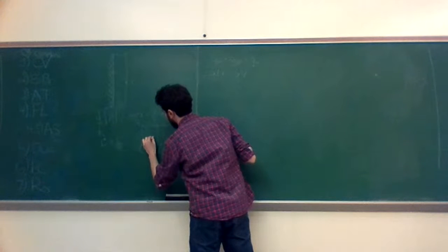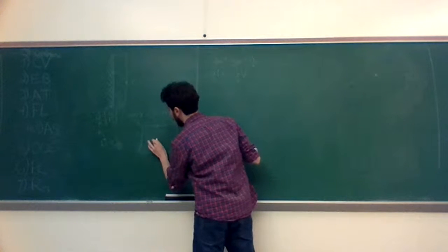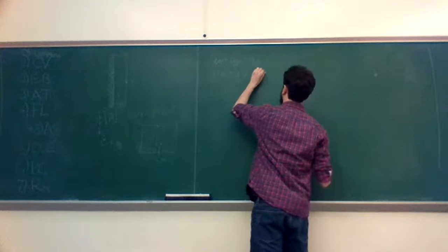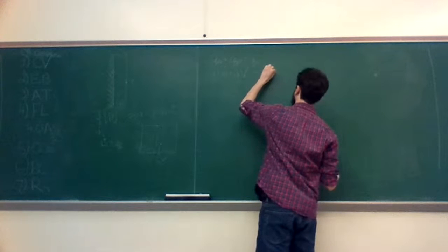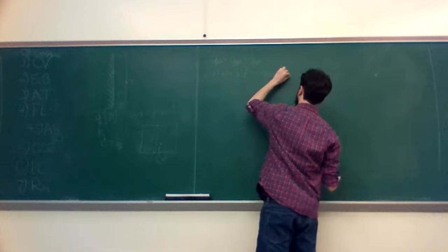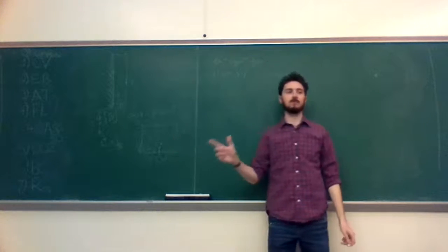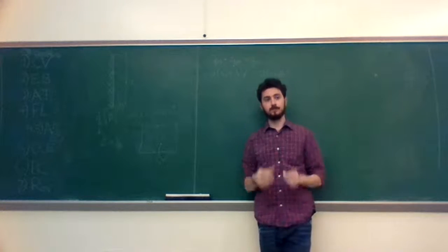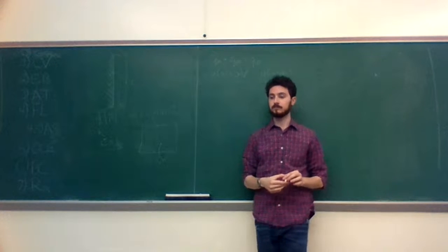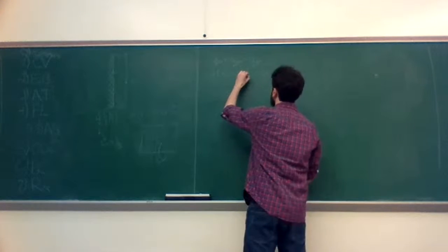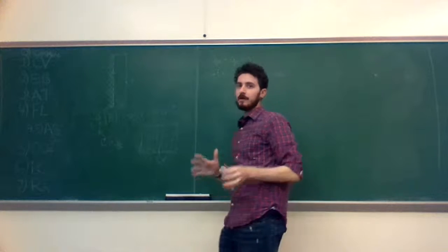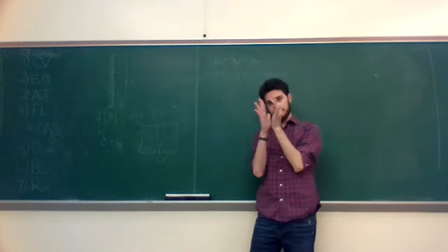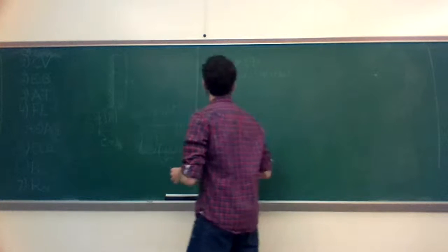So we've got a control surface here, right? A control volume here, and there's another control surface at x plus dx. Wait, so you're saying that the volume is the volume of the control volume? Yes, for this control volume analysis, we're just dealing with that little volume. So I'll write that V sub CV, the volume of your control volume, which is differentially thick, but full area. It's the full area of the slab, but it's just a tiny thin slice of it.